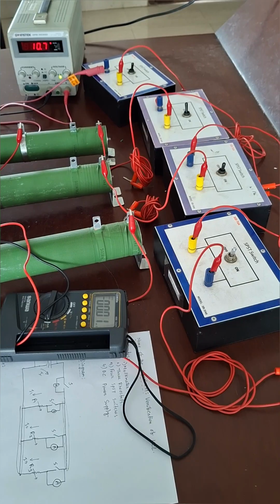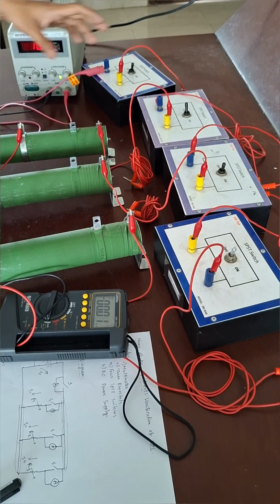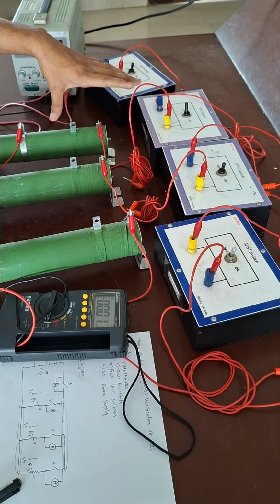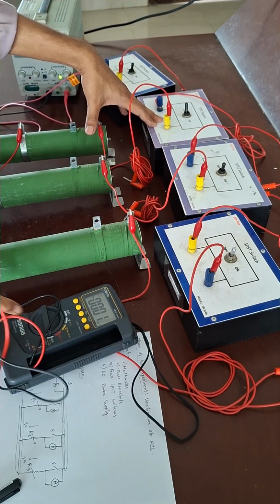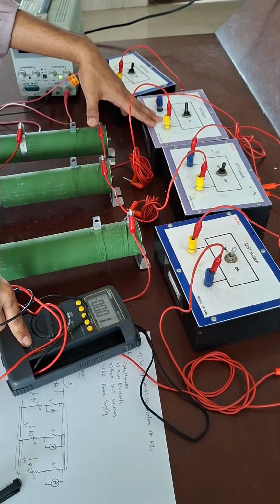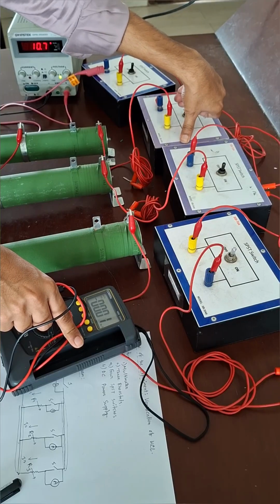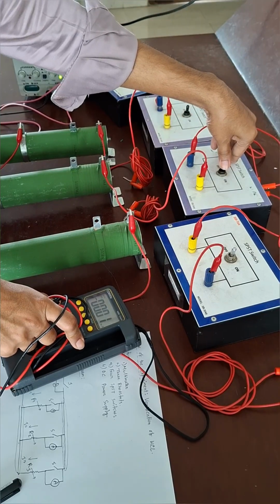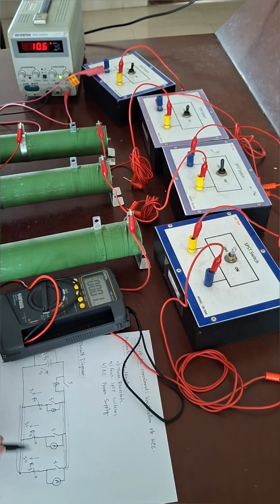Okay, so we have seen that this SPST switch or the first rheostat current flow is currently off, and if we connect the ammeter across this switch, the current will flow across the multimeter and we can see the value. So now we will turn on this rheostat and turn off the second one to measure the I2 or the current through the rheostat number 2.